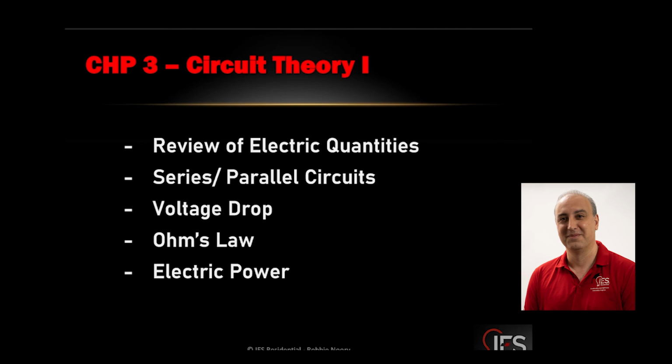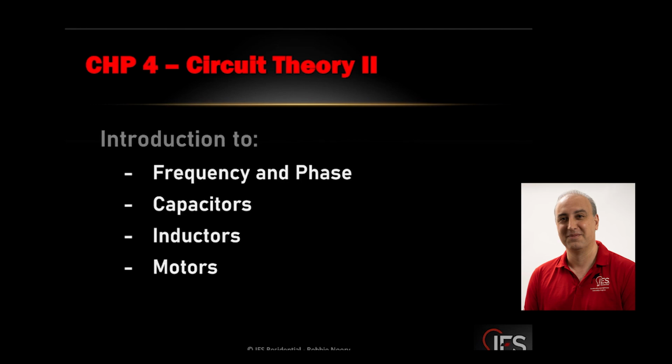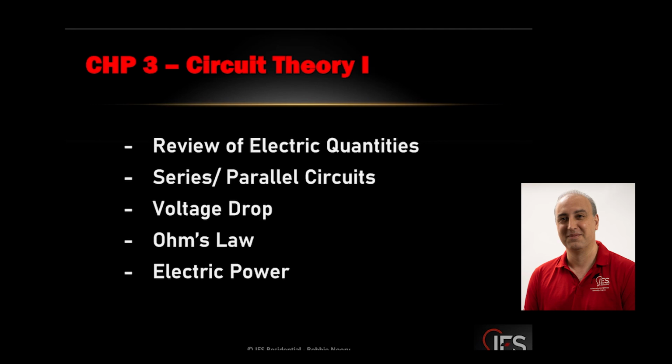That covers all the topics that we wanted to talk about today. We went over basic quantities and definition of AC, DC. We looked at series and parallel. Remember your bridges. That will tell you anytime you forget. Voltage drop: remember what resistance did to our wires. When they get long, resistance goes up, so we start worrying about actual voltage drop over long distances of wire.